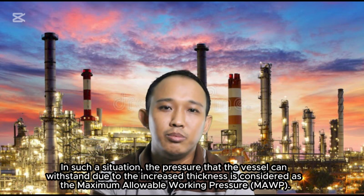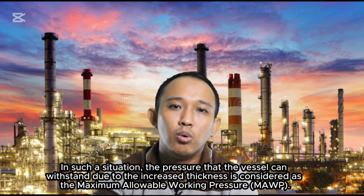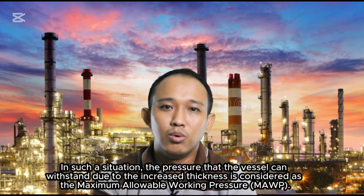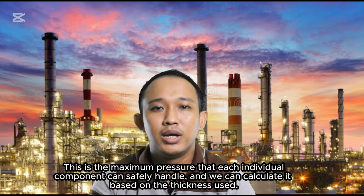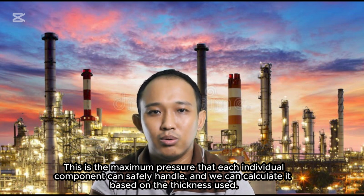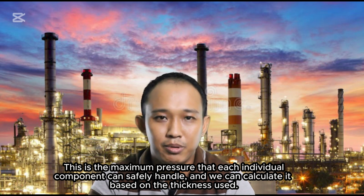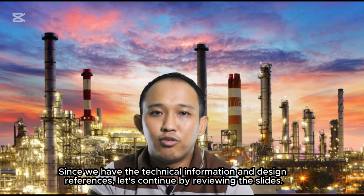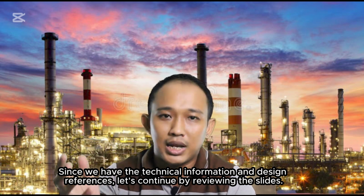In such a situation, the pressure that the vessel can withstand due to the increased thickness is considered as the maximum allowable working pressure, MAWP. This is the maximum pressure that each individual component can safely handle, and we can calculate it based on the thickness used. Since we have the technical information and design references, let's continue by reviewing the slides.